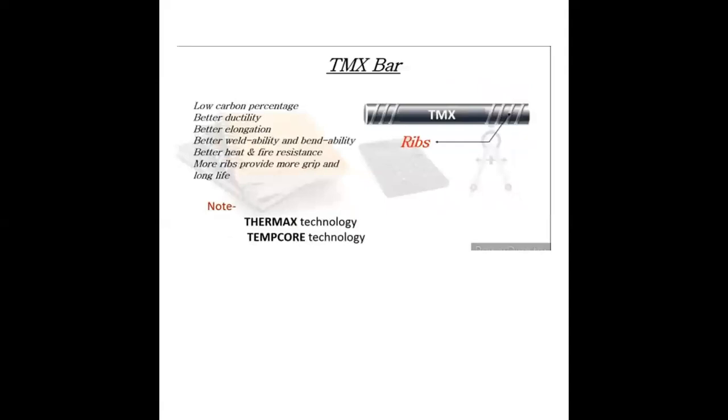And the next is the TMX bar, using Thermex technology. It has a low carbon percentage, better ductility, better elongation, better yield, welding and bending ability, and better heat and fire resistance. More ribs provide more grip and a longer life. I'm discussing the TMX bar.